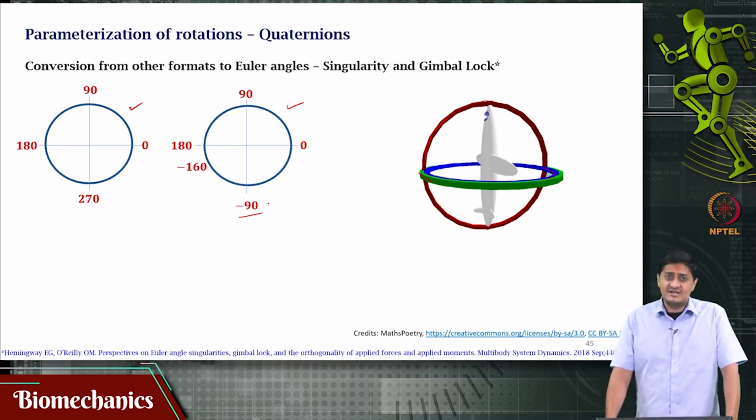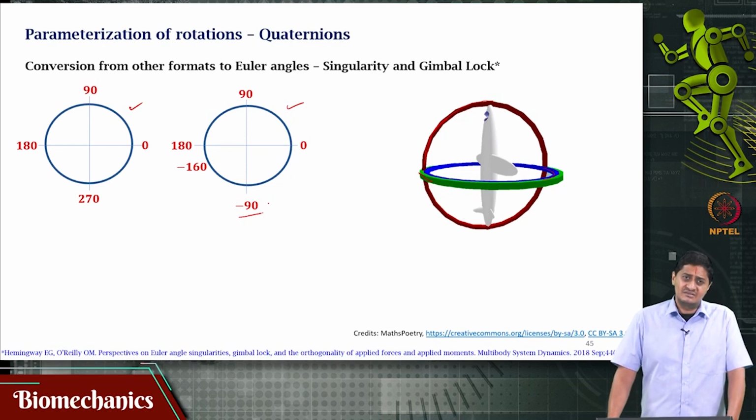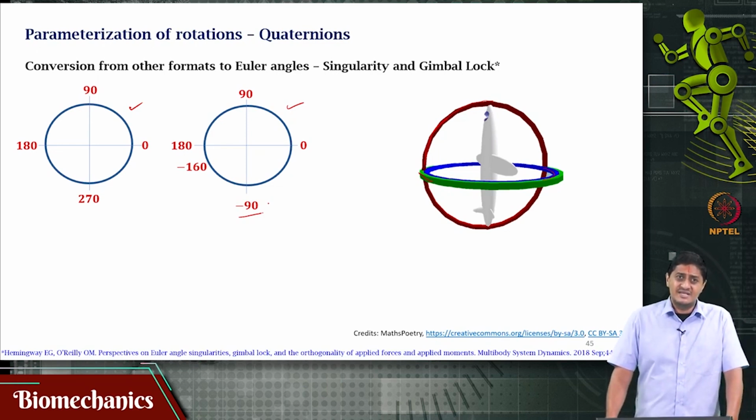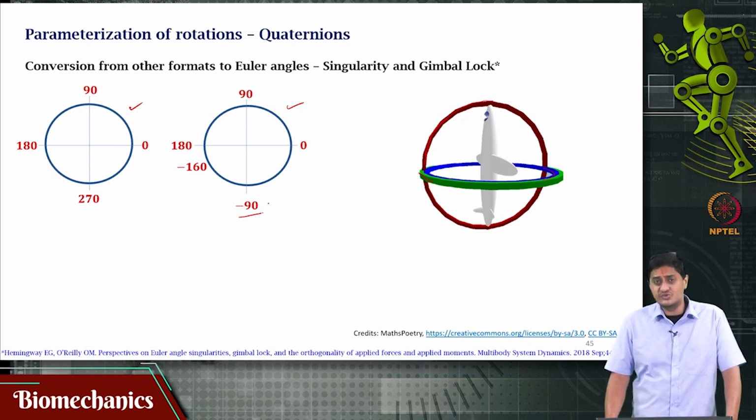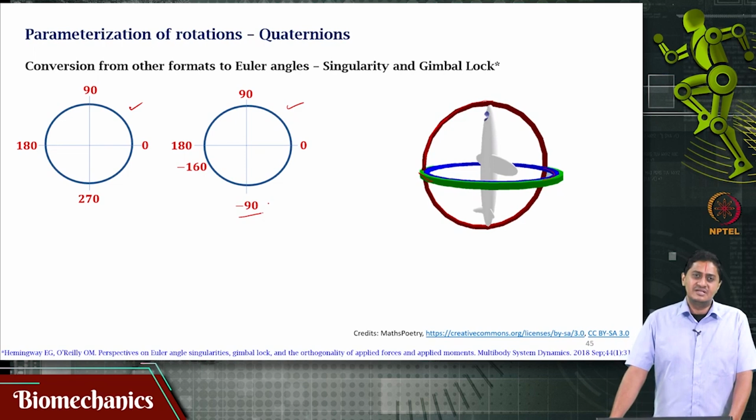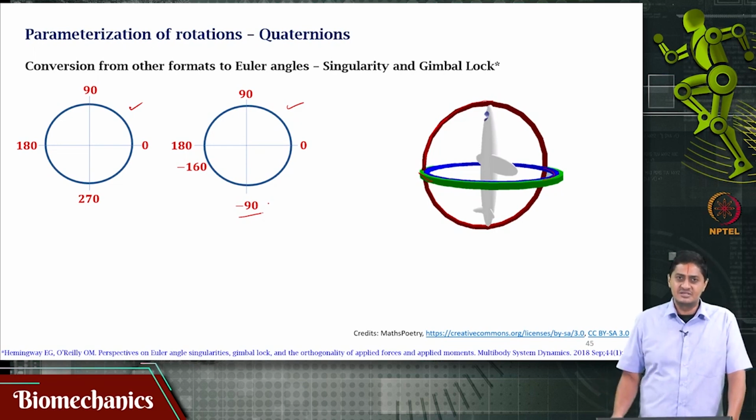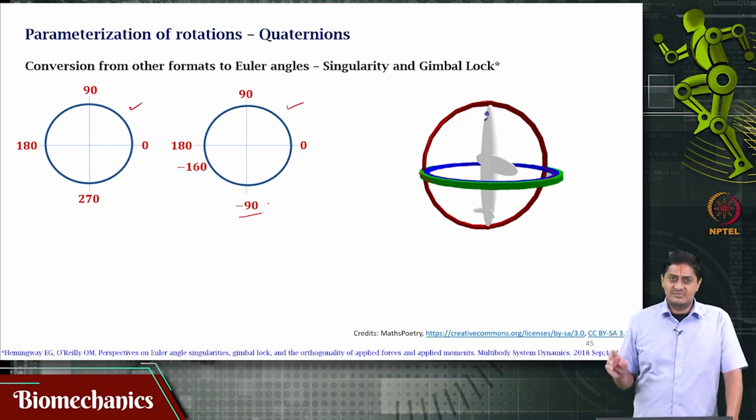They were very well aware that if you have a 3 degree of freedom system, there is a possibility that 2 of the gimbals will align, or there will be a gimbal lock situation that may be created. If it happens, then it will be required for this inertial measurement unit to be recalibrated or readjusted by measuring the orientation with respect to the stars.